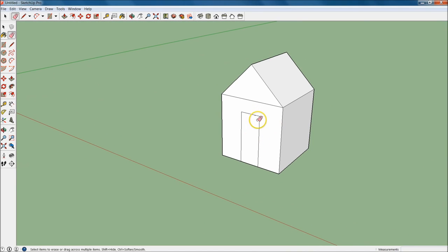And now you're thinking to yourself, okay, I think I made this door a little too high. I actually want it to be 7.5 feet. So what we're going to do now is use the move tool. If we go right over to here, you'll see these 4 arrows right here. Go ahead and click that. That's your move tool. Then we're going to hover over this line right here, and drag this down, make sure it's on the blue plane, the Z plane, and then we're going to drop it. And after we've already let go of it, that's when we're going to type in the 6 inches. Now again, we can do 0.5, or we can just type in 6 and hit enter.